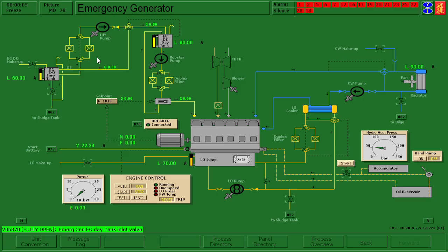It's a little bit complicated, or excuse me, not a bypass. This feeds back, so this is backflow, right? Well, it is a bypass going to the day tank. If the day tank is full, you'll bypass back to the service tank, so the system will continuously be circulating.